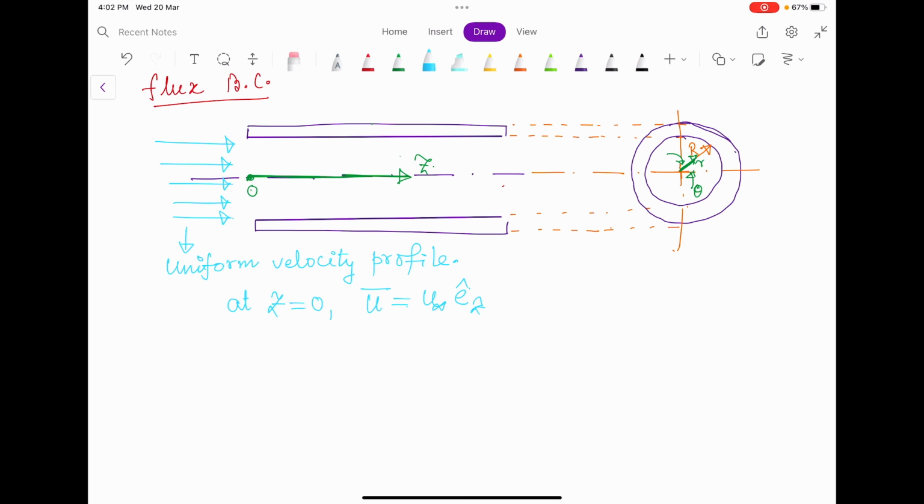Now I have already taught you the boundary layer theory in the external forced convection. Now you know that the moment the fluid is in contact with the plates, there will be boundary layer formation, right? So there will be hydrodynamic boundary layer formation. Now here, unlike the flat plate, we have the confinement. In the flat plate we did not have any other confinement, but here we have two boundary layers growing simultaneously. At a point they will meet, okay. Now what is the difference? You must have studied this in your fluid mechanics when studying the Hagen-Poiseuille flow. So here I will not derive the Hagen-Poiseuille flow. If I get time, then I will derive it in this course only, in some later video, okay.